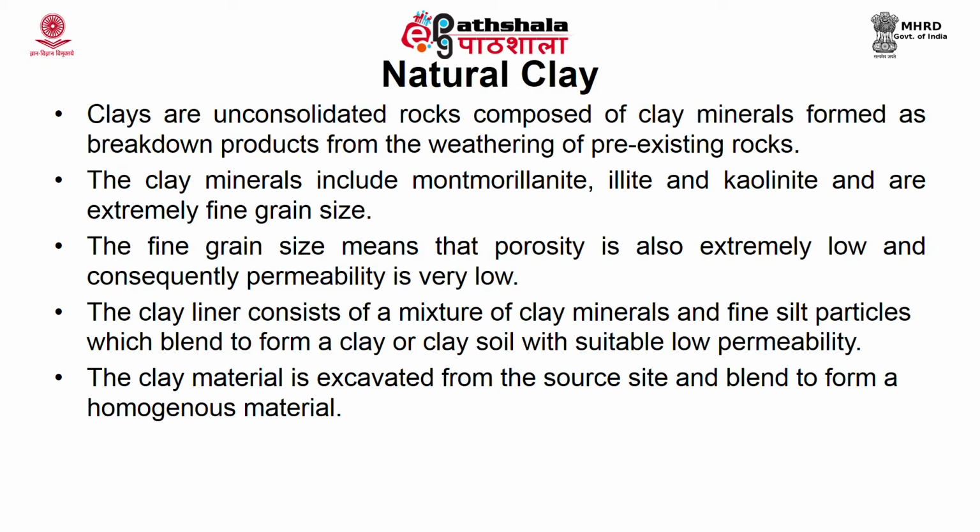When they start swelling, the air space between these grains is removed. The void space will be blocked and the interstitial spaces will be removed. As a result, the permeability will be decreased. That is the main significant reason why we are using clay as a liner material.